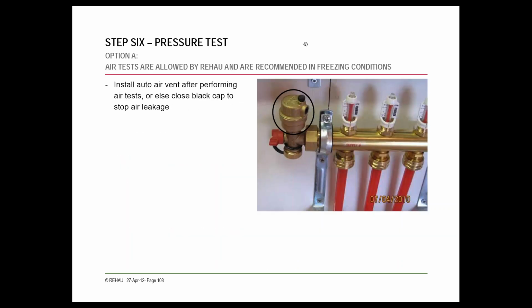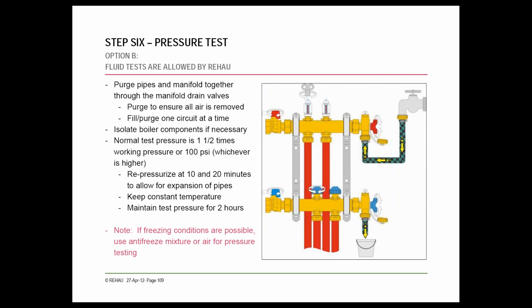It mentions real quickly here, just after everything's set, you do want to make sure that the air vents are working. You do not want to have this installed or open while you're doing the testing, obviously. So make sure you go back and open those after all the testing has been done, and bleed out any of the air left in the system.